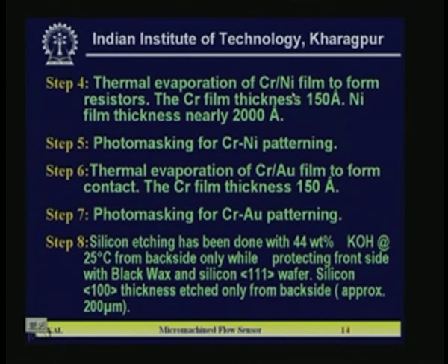What problem? Because you have already patterned the oxide, though not etched silicon. Oxide patterning means on the top and bottom surface there are some uneven places, grooves you have made by removing silicon dioxide from the top and bottom. If you do lithography in the next phase, you may face some problem, because photoresist will not uniformly cover the entire surface, and its thickness may vary over the entire surface top and bottom, and then exposure will not be uniform over the entire wafer, and in development and subsequent processes you can get some problem.